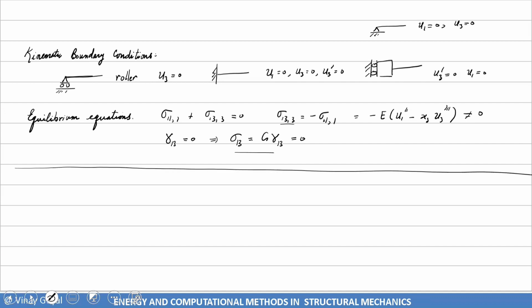And so finally, what I want to do is to talk about energetically conjugate variables. So in 3D, 1D axial bar, 1D Euler-Bernoulli, I get the following. In 3D, sigma ij is energetically conjugate to the strain epsilon ij. In 1D axial bar, I showed how N is the internal force quantity that resists external forces and is energetically